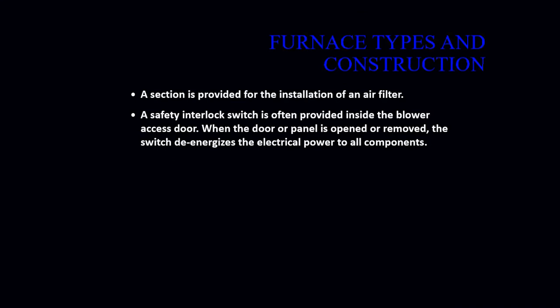We will also have a safety interlock switch that is usually installed on the blower access door. So anytime that door or panel is opened or removed, it's going to de-energize the entire electrical system for that particular furnace.